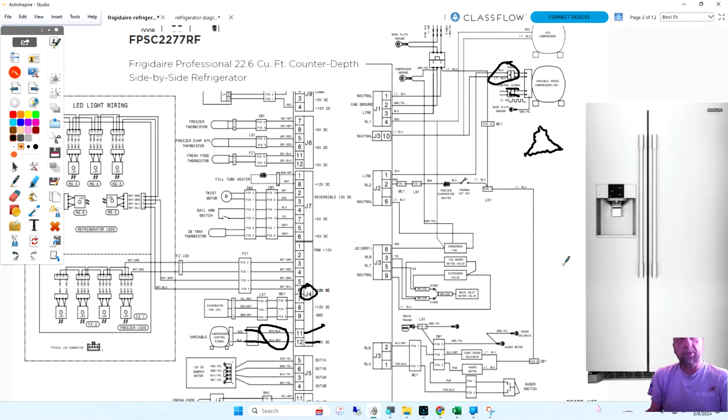I wouldn't want to rob the customer, but you've already installed this inverter on this unit. You either have to keep it for truck stock now or sell it to the customer. And it wouldn't be a bad idea here. It's just like changing a standard compressor. It's always good to change the relay and overload on a standard compressor, not just change the compressor and use the old electricals. So that is the variable compressor on there.